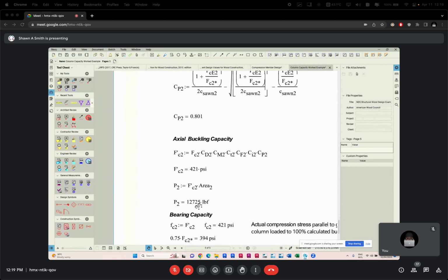Look at the capacity now. Should be larger. And that's logical. If you have the same material, the same southern pine, same length, same end conditions, the larger you go, the better off it becomes. And that's what design speaks to anyway. If a small one didn't work, we would have been increasing the size. So we only increase the size because we expect the bigger one to be better off. So the comparison really is that the larger one will have a larger resistance to buckling than the smaller one.